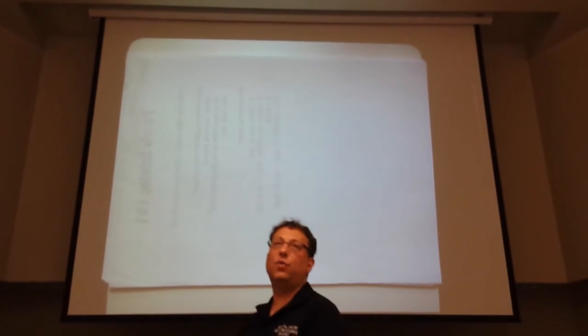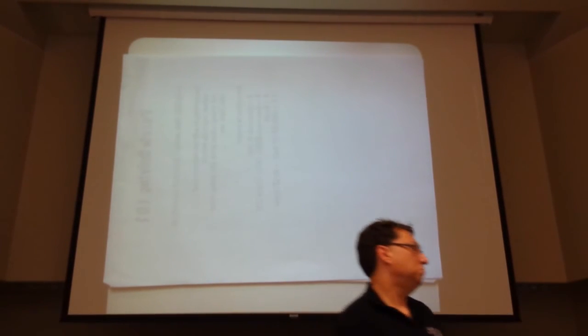There are other things in the book worth looking at. There are the Sallen-Key filters. Nice discussion. There are some slides about that as well, in one of our slides over the past couple weeks, with some pictures of those. It's a little more complicated design, but they use capacitors and resistors only to get second order effects. So more practical in some sense. Again, we usually try to get away from using inductors. So there are other circuit options, though the math gets a little more complicated.